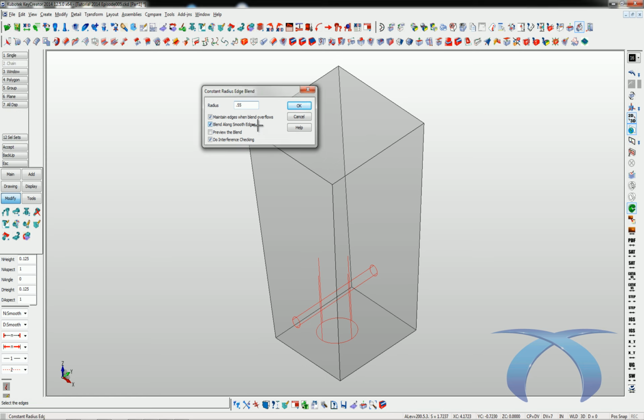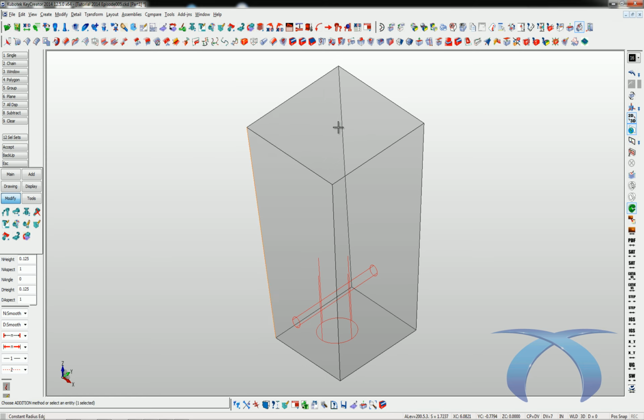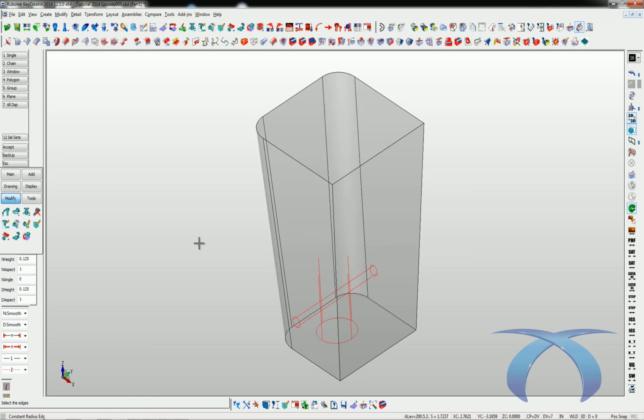So this is a decent sized lifter. Let's go with a 0.55 inch radius. That's a little bit more than the 1/2 inch. That way they go in there with a 1-inch cutter. They're not getting their cutter chatter.